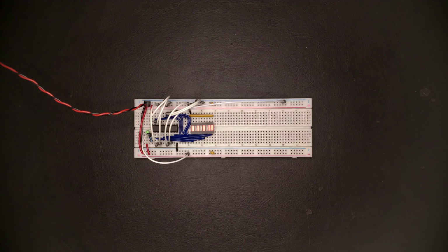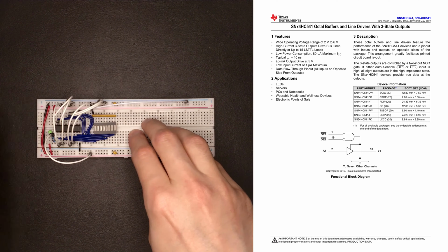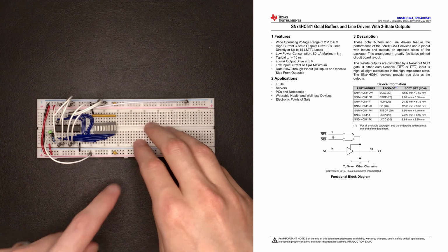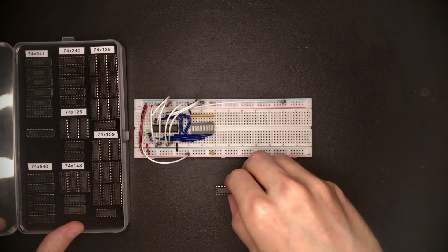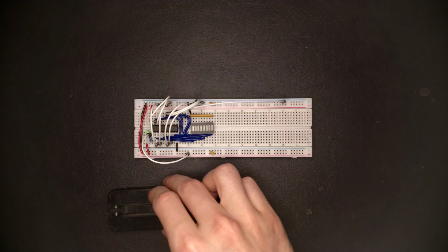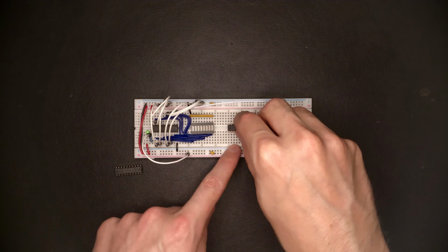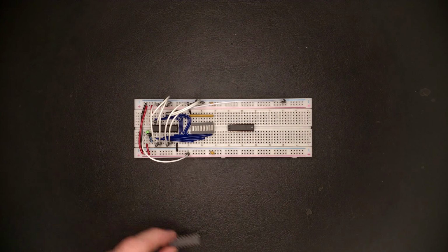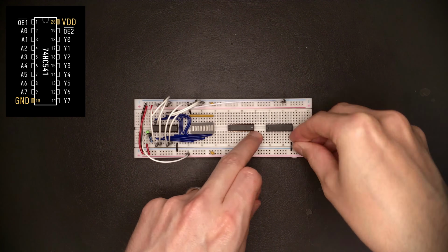In order to read out the value of the register, we're going to use a 74HC541 tri-state buffer chip, one for each read port of the register file. And what this allows us to do is select which register should drive its value onto the common read data bus. So let's place them to the right of the bar graph LED. They need power and ground connections.